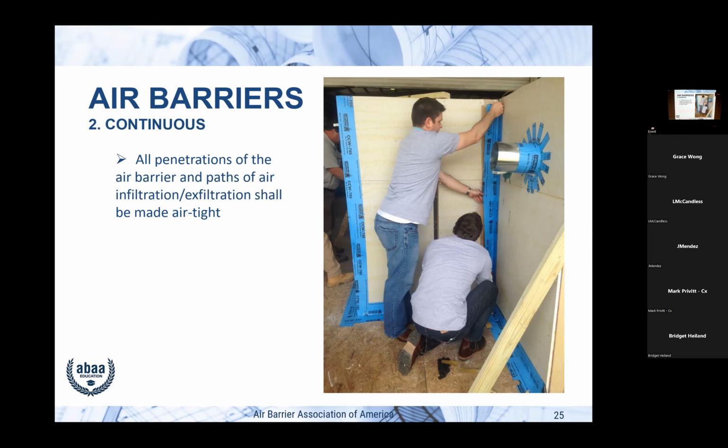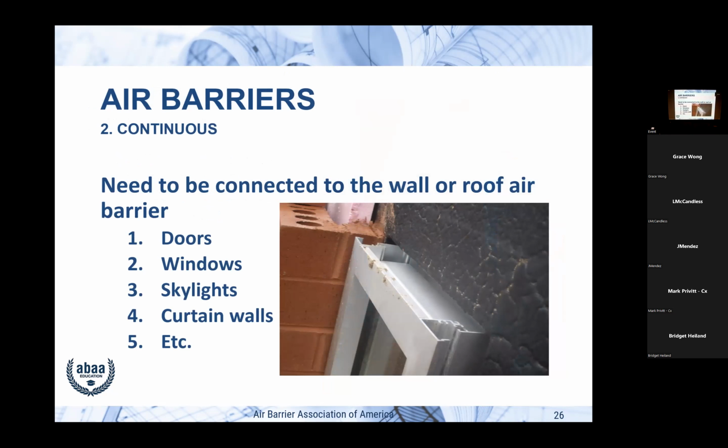One of the good things, and Andrew sort of showed, we're going a lot more to gunnable flashings rather than sheet flashings because sheet flashings trying to form in 3 dimensions are pretty hard. So that's the advantage of going to something gunnable.